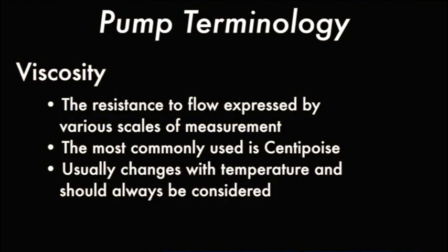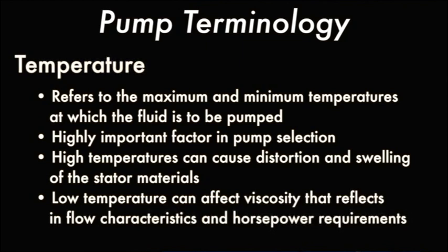Viscosity is the resistance to flow as expressed by various scales of measurement. However, the most commonly used is centipoise. The viscosity usually changes with temperature and should always be considered. Temperature refers to the maximum and minimum temperatures at which the fluid is to be pumped. This is a highly important factor in pump selection. High temperatures can cause distortion and swelling of the stator materials, and low temperatures can affect viscosity, which reflects in flow characteristics and horsepower requirements.